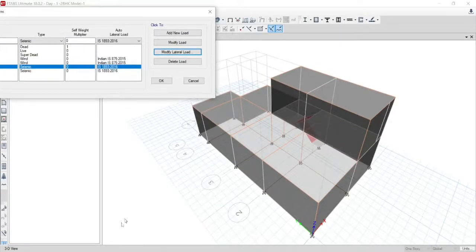Now if the earthquake is striking the building, we cannot assume that the earthquake hits at the centroid of the building. So for an object you will have a centroid. For the first floor you will have one centroid, and for the second floor you will have another centroid, and the center of mass. The mass center will be located at different points.